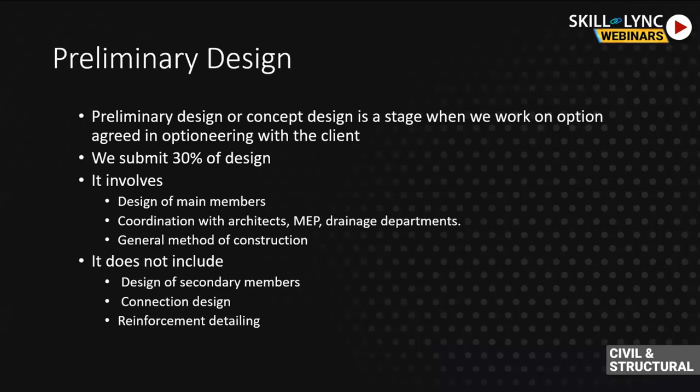The main things that you want to give in the preliminary design would be what kind of elements you are planning to use, what kind of span there is, whether it is a 6 meter span or a 7 meter span, and the total load that you'll be expecting on your foundation. So someone from geotech can also give you a tentative design for your substructure.